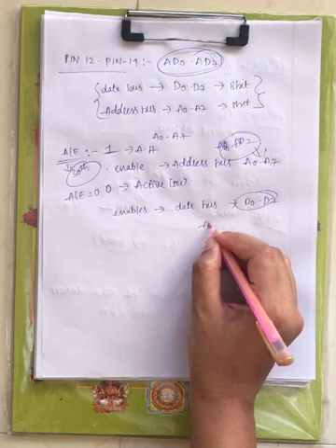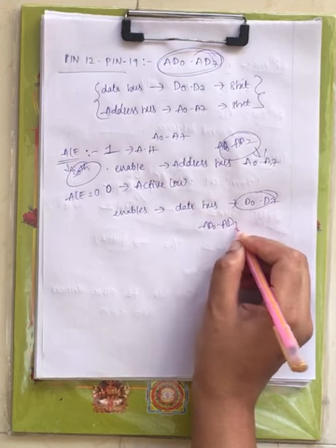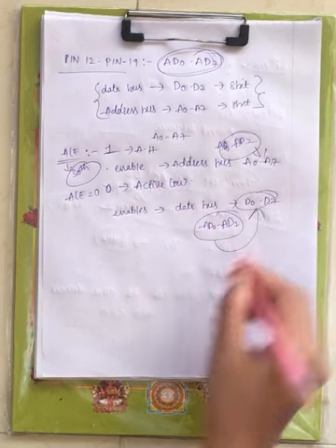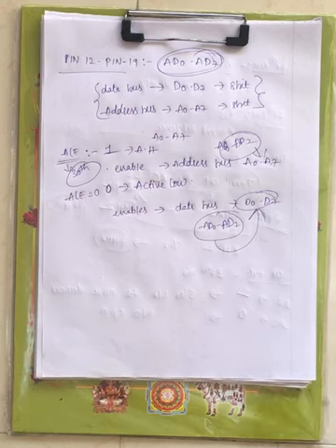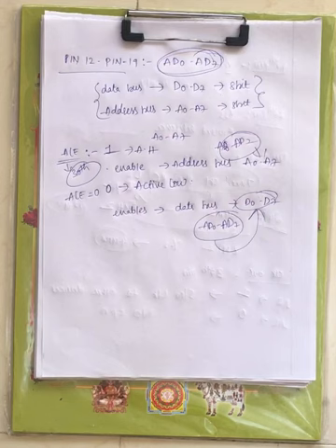Whether to carry lower order address or data bits is decided by the address latch enable signal. When ALE is 1, AD0 to AD7 lines will carry a lower order address. When ALE is 0, AD0 to AD7 lines will carry 8-bit data, that is D0 to D7.